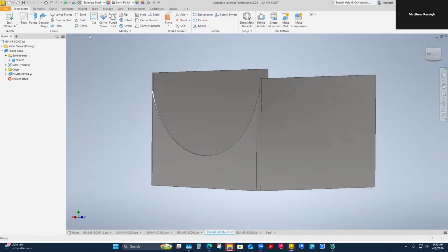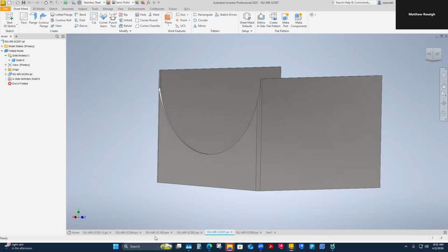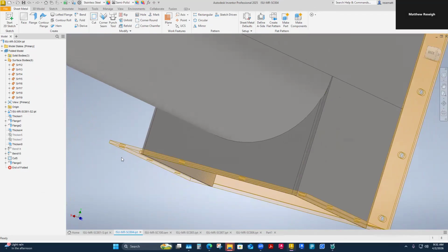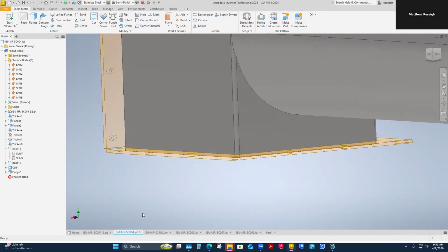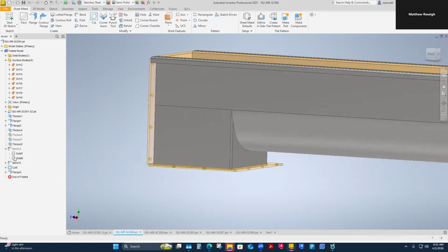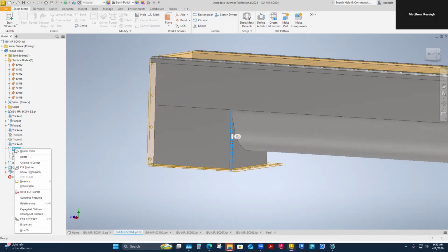And if yours is not, that's good, because originally yesterday I wasn't having too much issue with it. Let me see. You're getting that as well. So I'm back to my original part here and I'm troubleshooting it just a little bit. Come back to this and see if you've got a grayed out bend. I know I'd have grayed out thickens because those should technically have taken on and overridden those separate solids. But this bend should not be grayed out. That definitely is causing a problem. That should be an active bend.